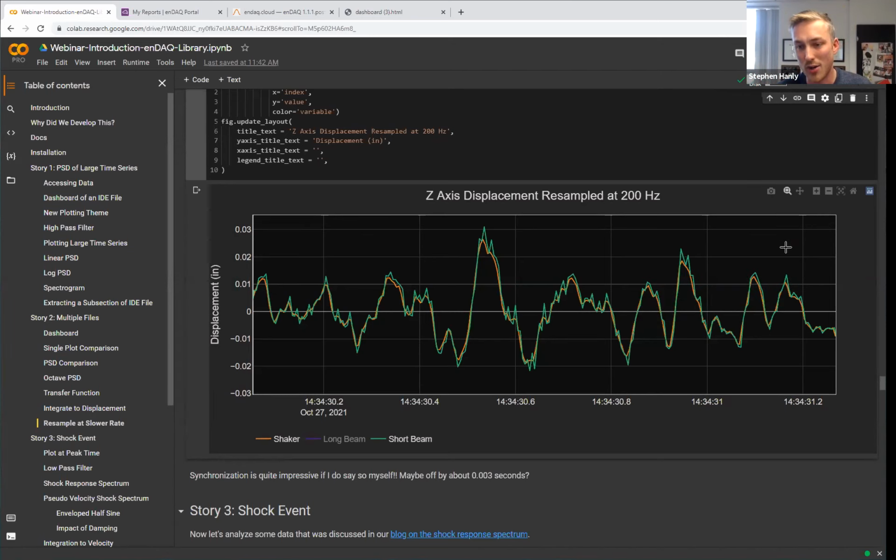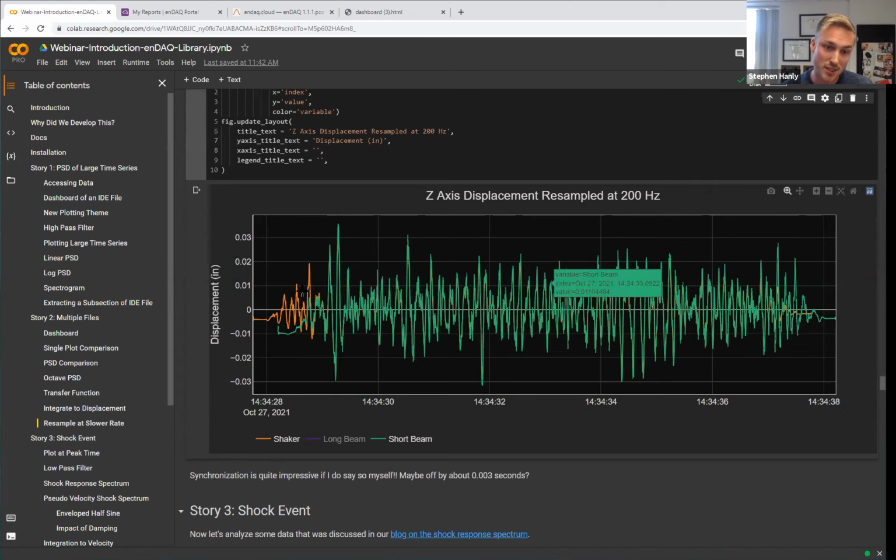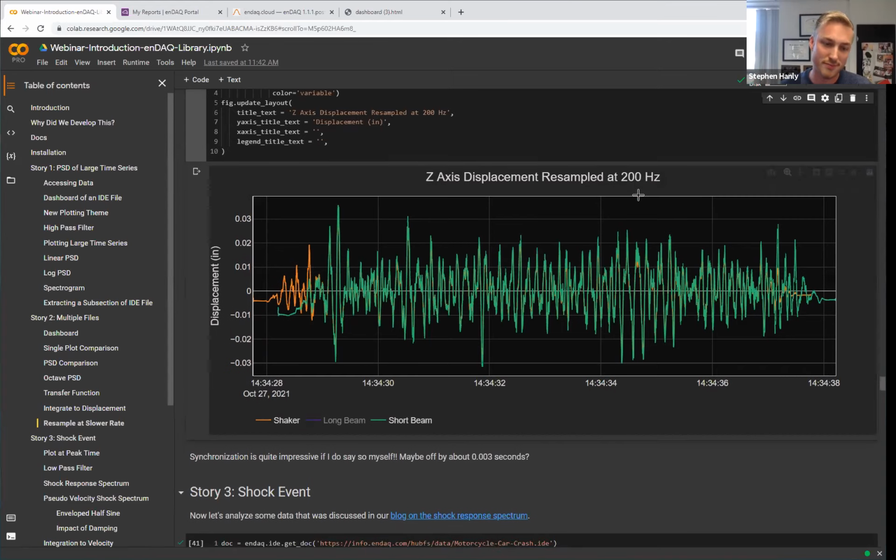And what I also want to call out is that this is remarkably synchronized. I didn't do any manipulation to the time data. I resampled it at a frequency, but I didn't shift the start times. So it's synchronized. And you see here the start times of these two recordings are off by about a second or two because I pressed the button on two of them like this, and then I only have two hands. So I pressed the third device a second later. But just from the UTC time in our device, saving the calendar time, you have remarkably well synchronized data to within about 3 milliseconds, which I think is pretty cool.